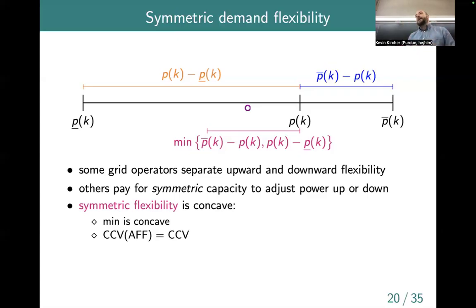So for this reason, power grid operators typically maintain some flexibility that can quickly ramp up. So this might be a gas generator or a hydro turbine, something like that, that can quickly produce more power if it detects undersupply. And actually, it may use what's called automatic generation control, AGC, where it's just monitoring the frequency on the grid. And automatically, if it locally measures 59.9, it just increases power production a little bit. But you could also do that with demand. So rather than increasing the supply from a hydro turbine, you could just decrease the consumption from a bunch of air conditioners, and it would have the same effect. Sorry, that was a very long explanation of a short question, but yeah.